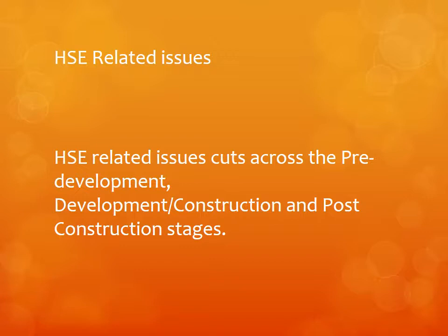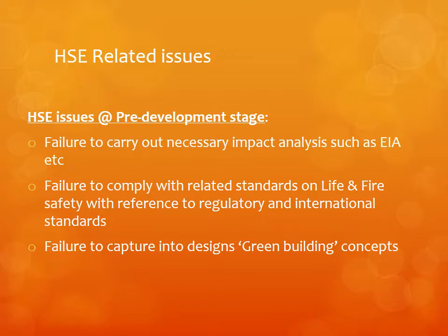HSE related issues cut across the pre-development, the development, construction, and post-construction. At the pre-development stage, the HSE issues basically are the failure to carry out necessary impact analysis such as EIA, environmental impact assessment, failure to comply with related standards on life and fire safety with reference to regulatory and internal standards, and failure to capture green building concepts into designs. So these are usually issues that you must look into at the pre-development stage, at the design stage, you understand.